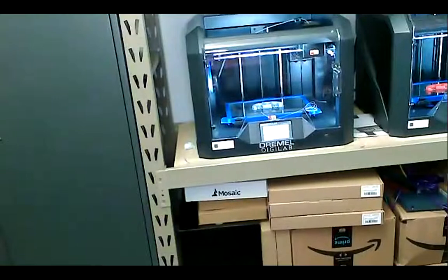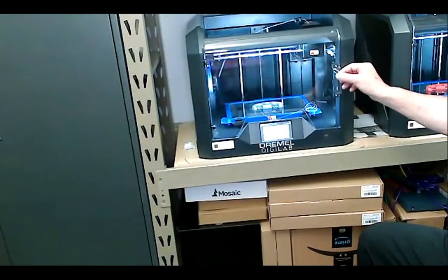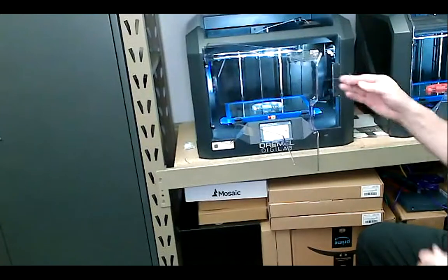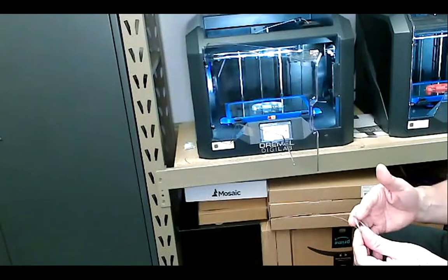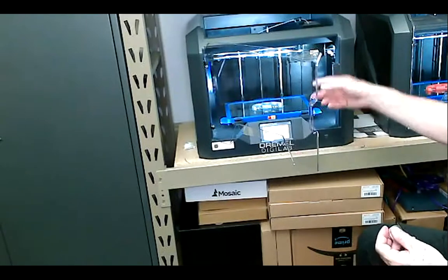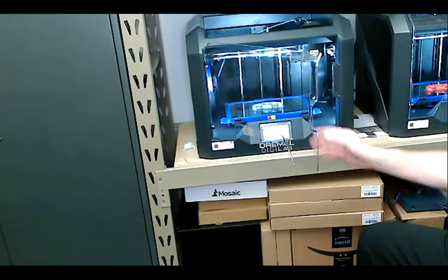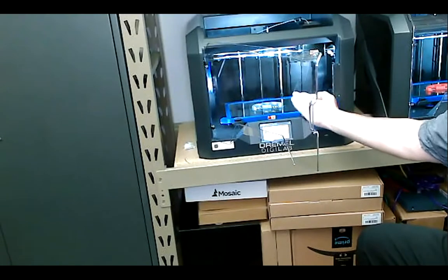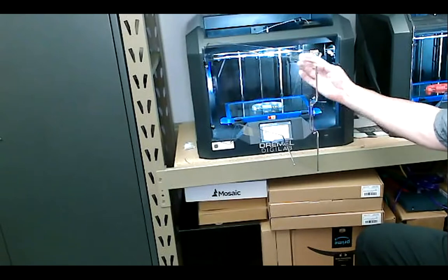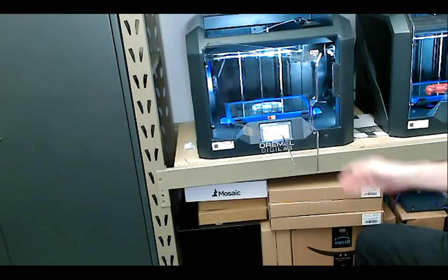If I take a look at the palette and I move the camera over to one of the machines, here's one that we printed last week. What I typically do when I start off in the morning is I'll go through and purge out the material by changing the filament. So I'll come in here and load the filament and purge it out. As you can see, it's starting to come out here. It comes out like fishing line, and it's soft. You can kind of stretch it. It's hot.